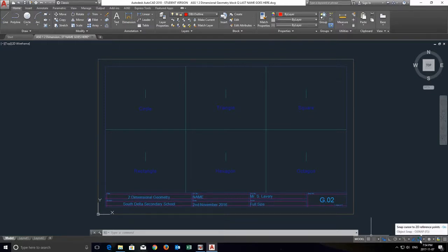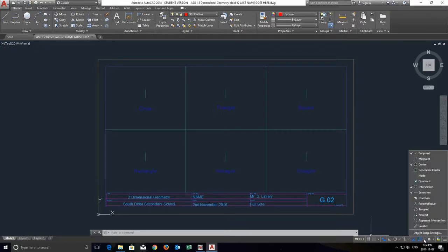This is our most important one though. This is called OSnap or Object Snap. Now that's going to be on, and I'm also going to make sure to do this. This little down arrow indicates that I need more things here. So I'm going to click on that and I'm going to bring up this menu. Now anything that is checked, that means I'm going to snap to those points. So you recall if you did the basic logo, that snap to end point is usually on, and that means you can just start drawing right at the end of another line.